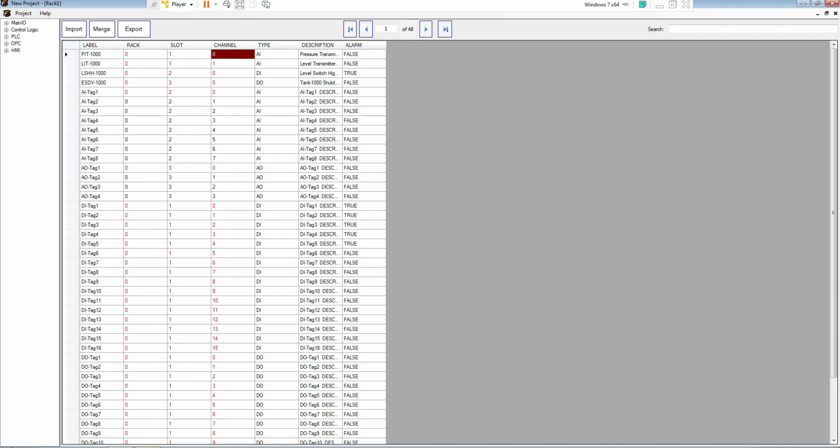especially in large systems. So if I go here and say, well, I'm going to assign it to, let's say, 10. Looks like it's still used. So we have here 0 to 15. So if I go and put this to 16, you can see now it's happy and there's no problem there. Same if I say 17, the same thing. So now this is fixed as well.